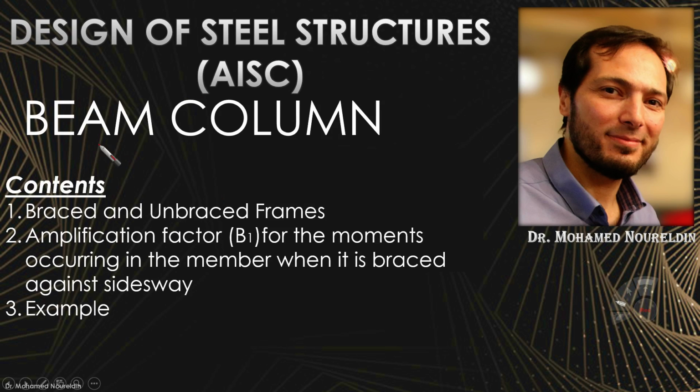And still we are dealing with beam column. Today I'm going to talk about the contents of today's lecture, which is related to the concept of braced and unbraced frames. And then I'm going to talk about the amplification factor, B1, which is commonly used for the moments occurring in the member when it is braced against side sway.